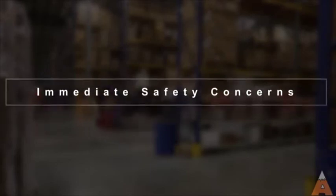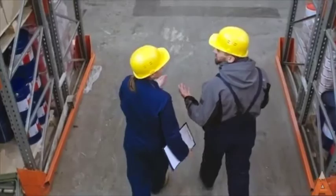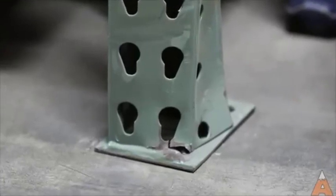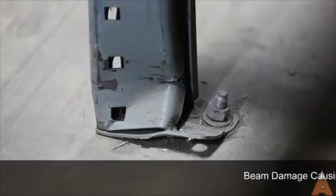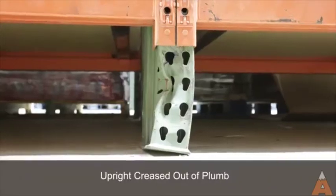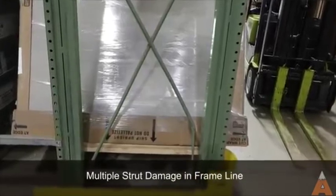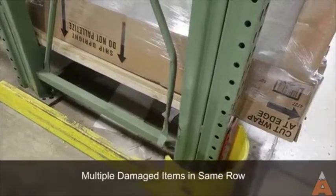If you find any severe damage or immediate safety concerns, we recommend unloading the rack until it can be properly repaired. General guidelines for immediate rack safety concerns include rack that is not anchored to the ground, severe beam damage where the beam is creased or buckled, upright damage where the upright is completely creased or out of plumb, excessive strut damage or multiple damaged struts in a frame line or row, multiple damaged items in a row or system.